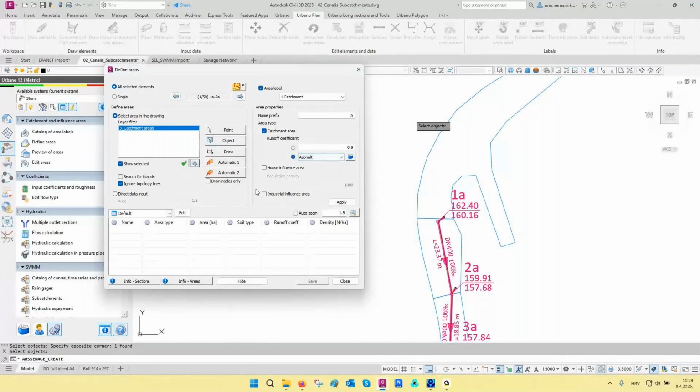And now I will show you the new option, which is called automatic. This function checks whether a node, it can be any type or just drain. And I will select this checkbox to select only drains. So the function checks if a drain is located within a closed area. And if it is, it assigns these areas to the node outlets section.